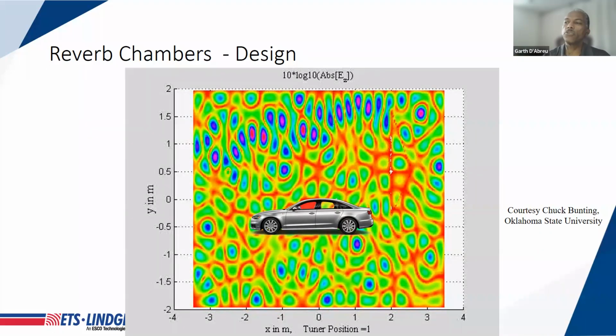Another technique that's introduced in this document is what we call the high-speed stirring or fast stirring, where you have a stirring mechanism that stirs the modes very, very quickly. And if you think about what's happening, if you stir the modes very, very quickly, you're creating this sort of average field density within the volume of the cavity, which normalizes or equalizes the field strength within that volume.